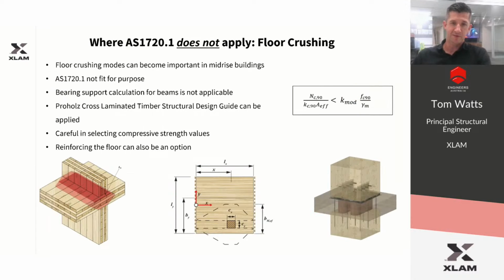So moving on to aspects of CLT design which aren't covered under the DTS pathway: floor crushing. When you're looking at mid-rise CLT buildings, floor crushing is one of those applications that does start limiting the height of CLT buildings, depending on how you're looking to construct it. AS 1720 is not intended to cover this aspect of design, and the best references that we believe are available for this are what's covered in Eurocode and the ProHolz recommendations and guidelines.